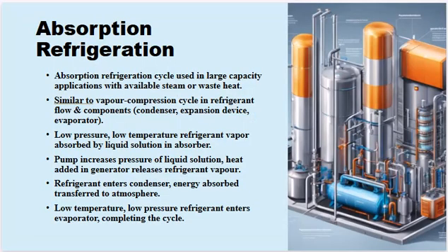Let's cover absorption refrigeration. Absorption refrigeration is a specialized cooling system ideal for large-scale applications where steam or waste heat is available. It shares similarities with the vapor compression cycle, using components like the condenser, expansion device, and evaporator, but replaces the mechanical compressor with a chemical process.